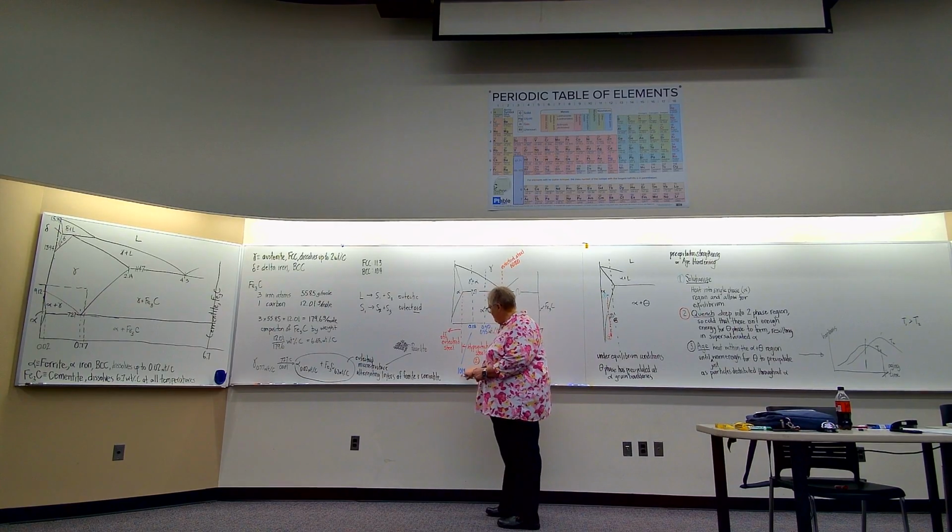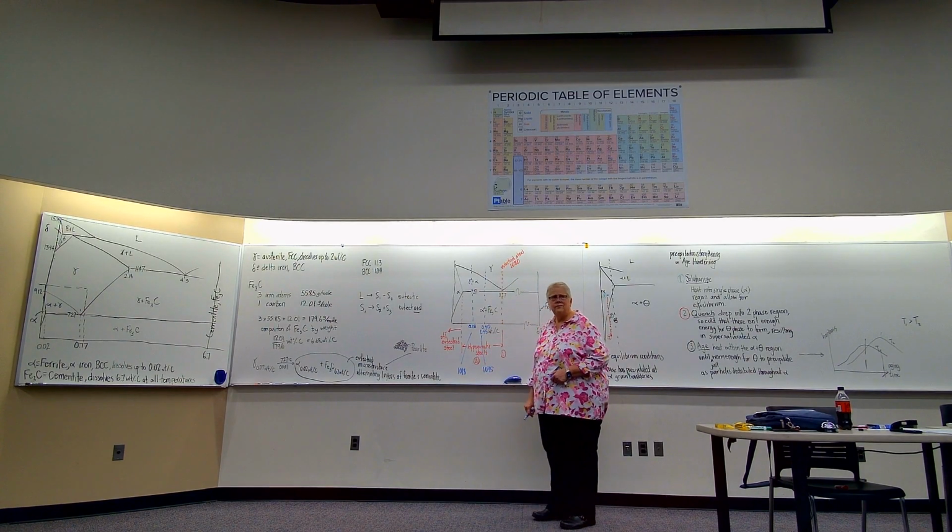When the 10 means just carbon, that's the only thing used as an alloying element. You'll also be dealing with 1045 steel, also plain carbon steel. We can compare those two, knowing that they only have carbon, so the only difference is the amount of carbon.